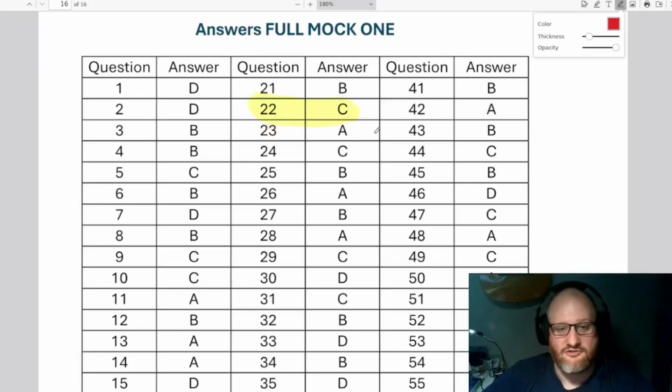So the key thing to remember here is that certainly within the full syllabus, it's only really FM signal that can get through a frequency multiplier. If you're interested in this, you can go read up on it. You'll find that there are ways of doing this with amplitude modulation as well, that allows AM or sideband signals to get through it to be multiplied up, but for the full, just bear in mind it's only FM that can make it through.